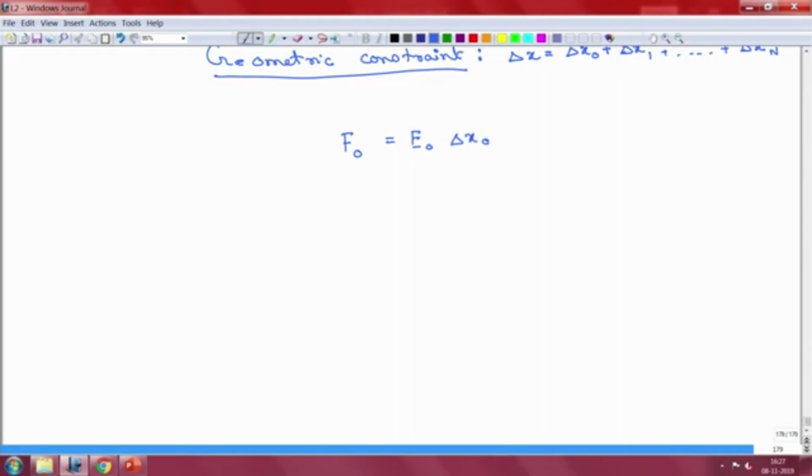Now, the equation for all the different Kelvin Voigt Meyer bodies is going to be the same, and the force here is going to be given by E 1 plus eta 1 times the differential operator d into delta x 1, and this is going to be continued all the way till all your n elements are complete.